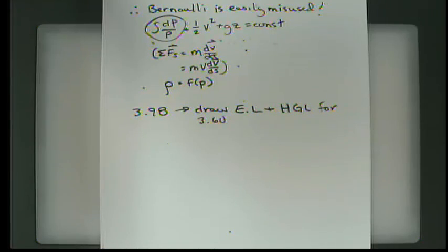All right, so we already know from that discussion that we can't go below vapor pressure or we're going to get that cavitation effect. We talked a little bit about that last time. So it says, if viscous effects are neglected, at what height h will cavitation begin? And to avoid cavitation, should the value of D1 be increased or decreased?